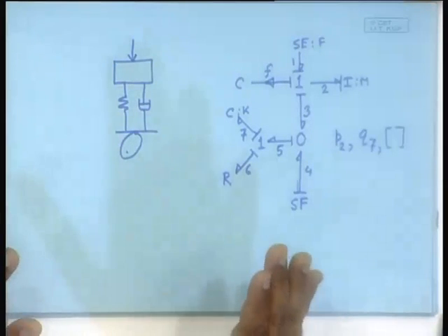So, in these situations we will need to do that. A whole circuit in which there is a capacitor, you want to observe the current through that capacitor. What will you do? Current is proportional to the momentum. Therefore, you want to measure the current means somehow you have to get the momentum as a state variable, but momentum is not a state variable of a capacitor. What do you have to do? You have to connect a dummy inductor through an activated bond. The moment you do that, it will generate the necessary variable. Is the question clear now?